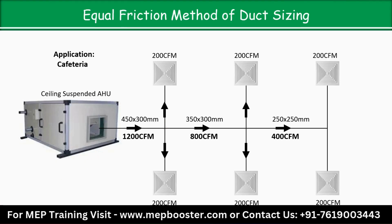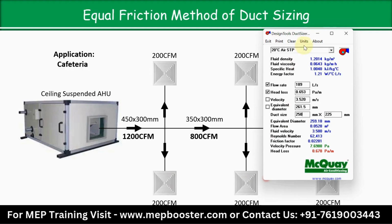So that is why here I am opening the McQuay, and each diffuser CFM is 200. First change the unit and write down 200. Now here I am considering height 200. You can also select 250, no problem, because the main duct height is 300 and the branch duct height can be 250.